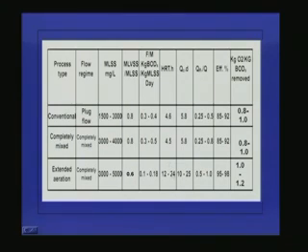And theta c here is 10 to 25 days. If you see the theoretical theta c value in an extended aeration system, it will come almost infinity. And the recirculation ratio is 0.5 to 1. In most cases, the entire sludge generated in the extended aeration system will be recirculated. But practically, to avoid the accumulation of inorganic solids in the system, around 5% of the sludge will be wasted. That is why the recirculation ratio is so high. That means 0.5 to 1, that means 100% recirculation.